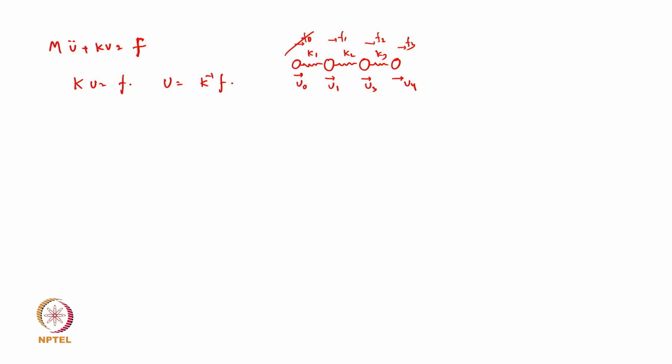Any doubt? So that actually shows you will not get any value of u. Also, in this case the stiffness is almost 0, which means your displacement is infinite. If you do f by k, and k is 0, then f by k, which is your u, becomes infinite. That means you apply the force and it will go. Where it will go, you don't know, because we have not considered the velocity and other things at all. It is an instantaneous process. Apply the force, it goes. Done.